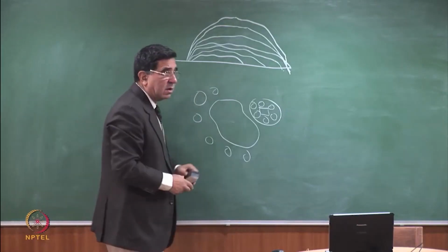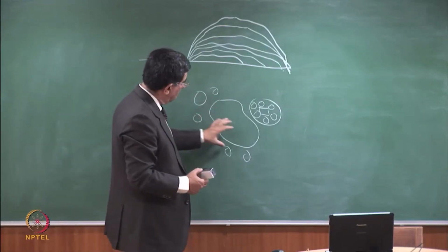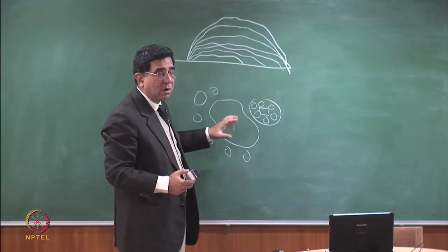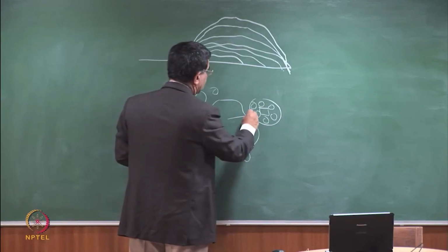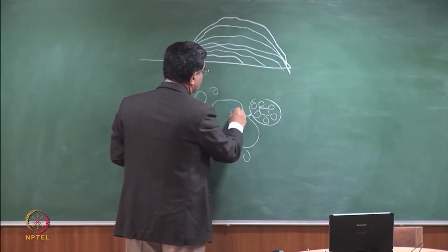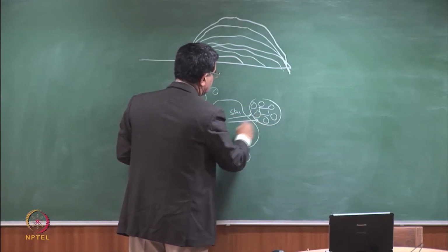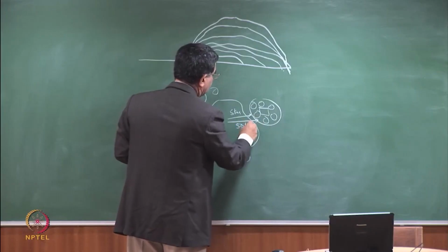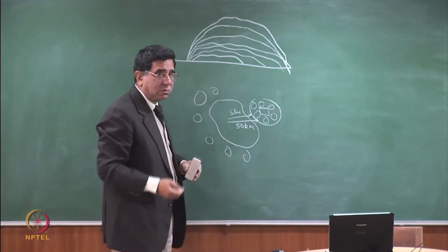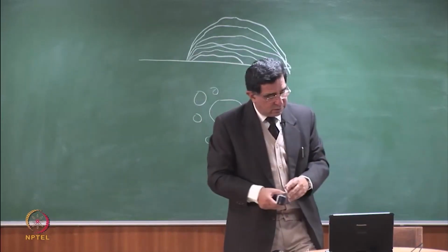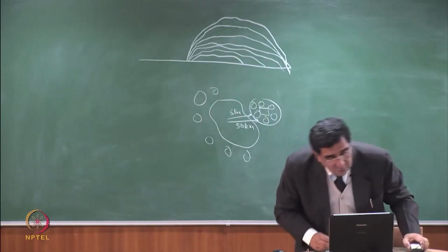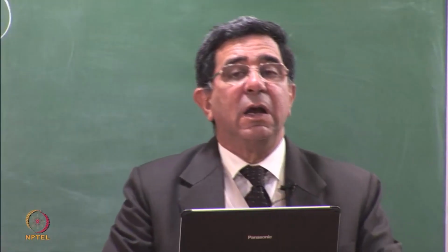units all around it. So that will depend on how the plan area of a city and how large it is, how large are the distances. If this distance is 5 kilometers, that is one solution, but if this distance is 50 kilometers, then you have another solution. So those solutions will be given to you by integrated solid waste management, where you can see how much are the transportation costs and how much are the processing costs.